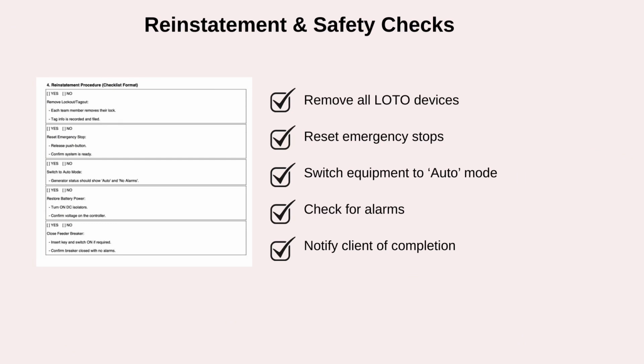It's not just about ticking boxes. If something fails next week, this document becomes your receipt. It says, "Hey, we followed the right process. Here's proof." A typical sign-off includes the name of the person who performed the work, the name of the supervisor or witness who confirmed it, time and date of completion, notes about anything unusual, delays, or follow-up actions. And trust me, if you don't include it, you'll regret it when someone asks who worked on this last. So yeah, don't skip the sign-off. It's the last step that makes your MOP official.